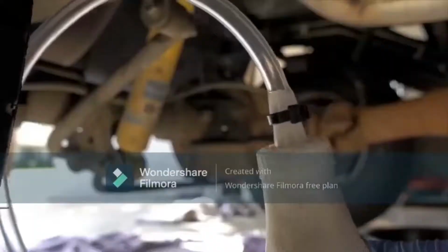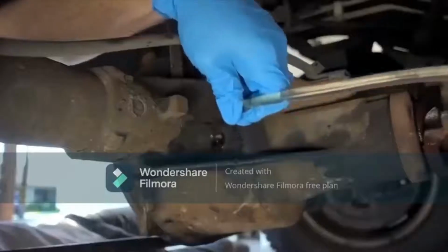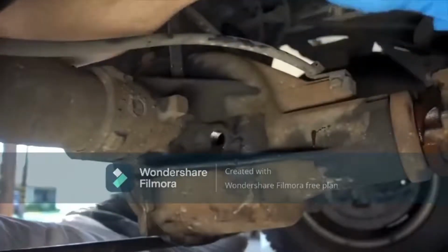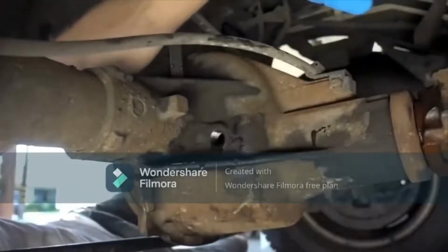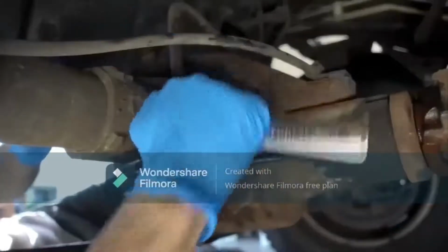Then refill the differential oil according to the manufacturer's recommendation. This process can be eased by attaching the diff fluid bottle to a siphon for the filling process. Once a certain amount of oil is filled, close the fill hole, then the maintenance process is complete.